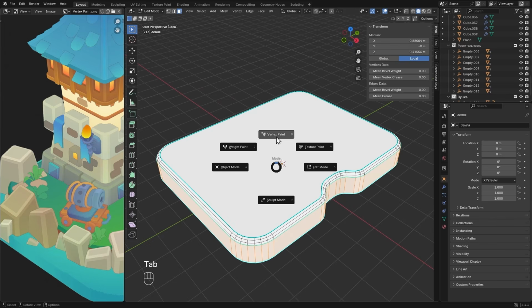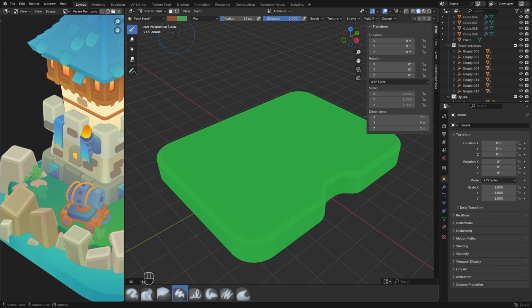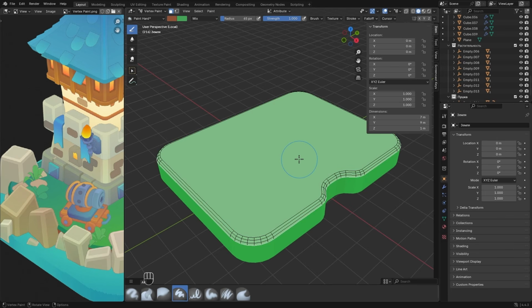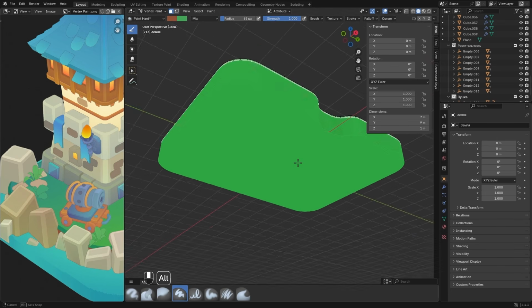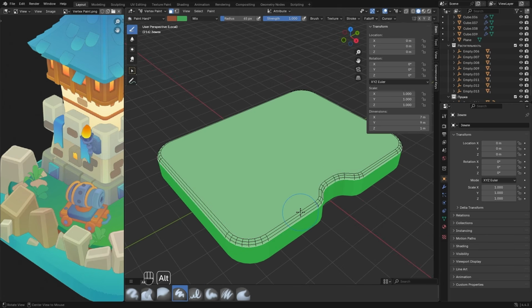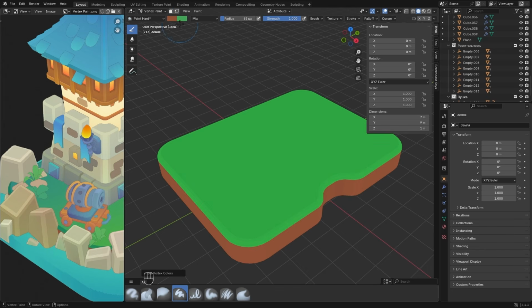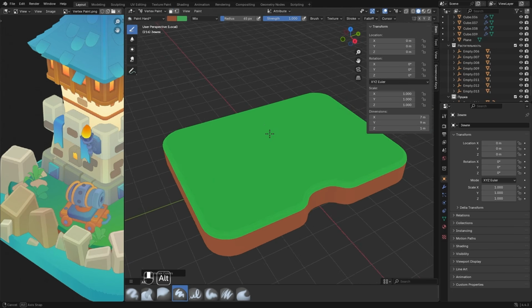I go back to Vertex Paint and activate the mask, Paint Mask, here. Hover over this icon, and we can see that the area that was selected remained unchanged, while the unselected part is highlighted with this white overlay. If we try to paint, we will notice that the overlay areas are locked, and use the Fill tool to assign the color to this part of the object. Let's disable the mask and look at the result.